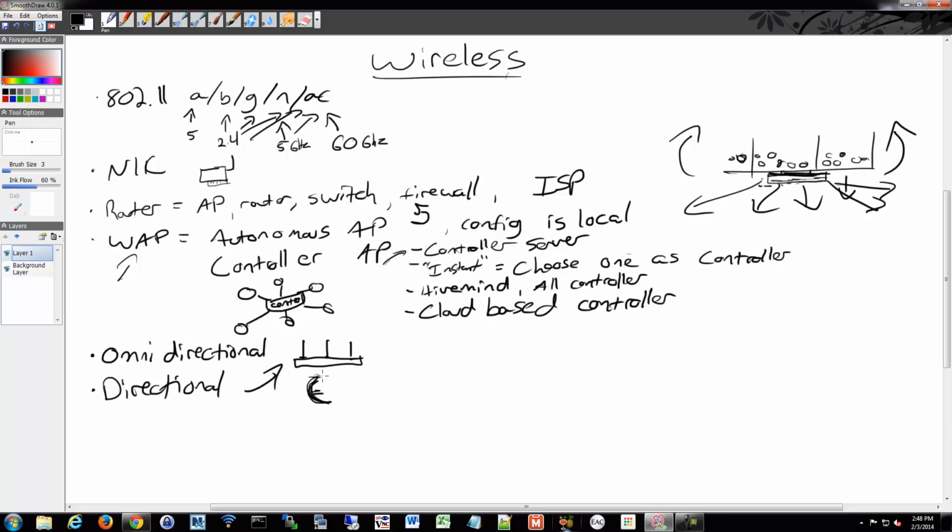The directional antennas are used majority for connecting between direct locations. So, for example, you have building A and building B, and you don't have some sort of fiber connection underground or something to them. You could use microwave communications between the two, and you can send wireless communication between them. That's one option. You can also do it just to spread directional traffic to some sort of courtyard or something like that.